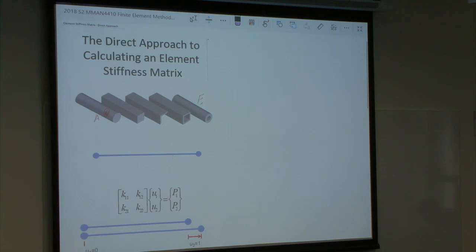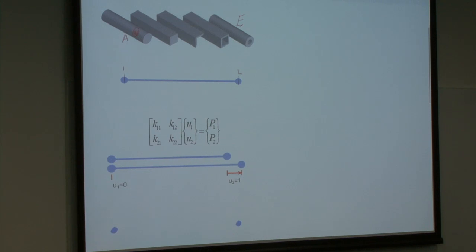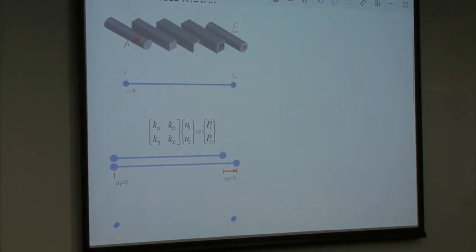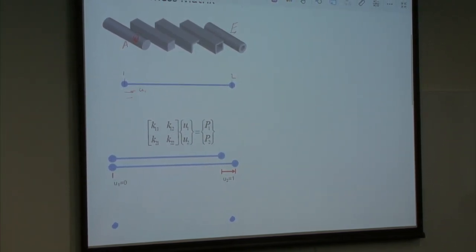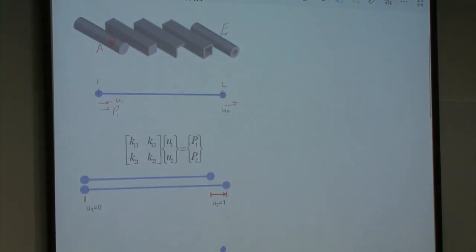If we're torquing or bending and we're interested in the response, we can't use bars anymore. We have to use beams. Basically, for a 1D with that, it's a beam. So we can model it down to this structure here. We'll give these nodes numbers, 1 and 2. So at either end of the length, there is a nodal number. At each node, we have some displacement U1 and some force P1, displacement U2 and force P2.